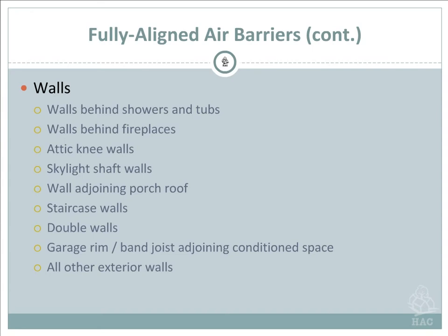I've seen so many fireplaces where, once that fireplace isn't in use, you run an infrared camera in there, and that wall is just red with all the cold air coming in around that fireplace. Another theory behind fireplaces: if you're in a room that's 80 degrees and you open that fireplace and build a fire in it, the temperature in the room probably drops to about 72. So take that into consideration when you're putting in those fireplaces. They should be closed boxes.